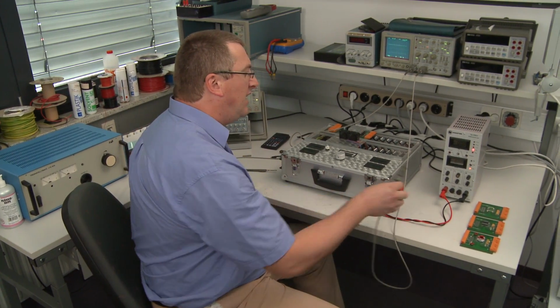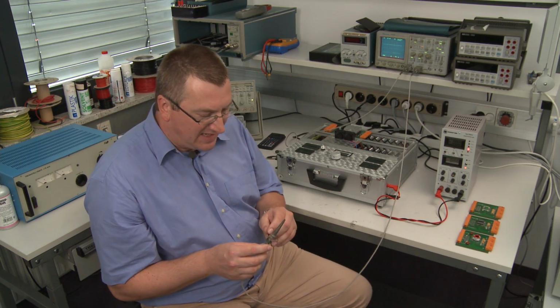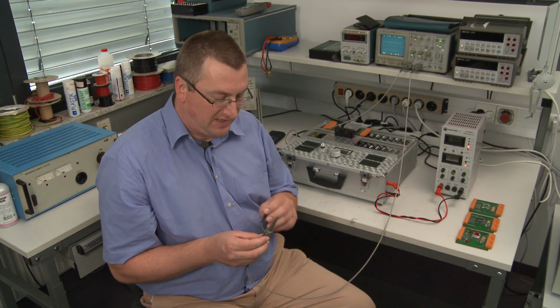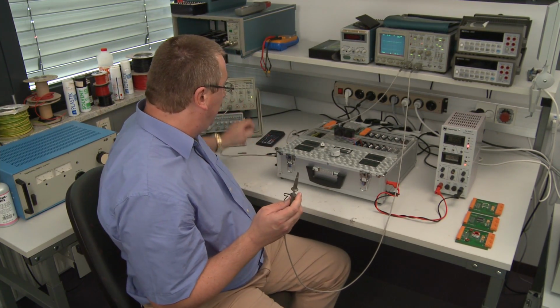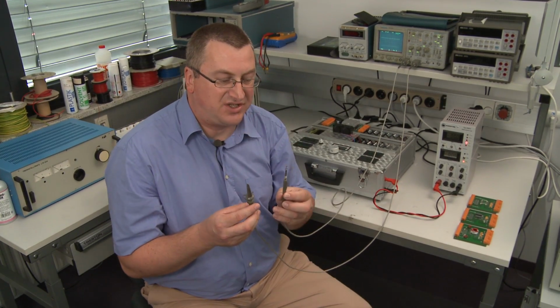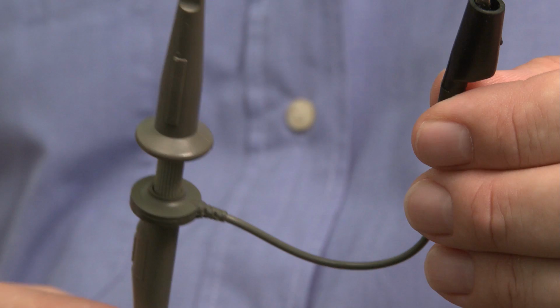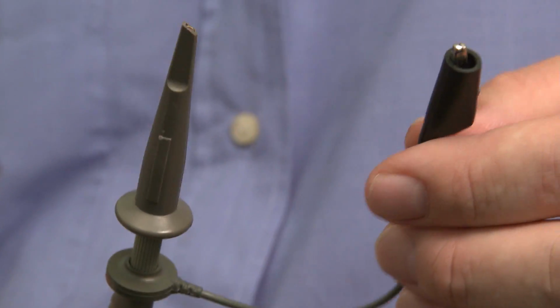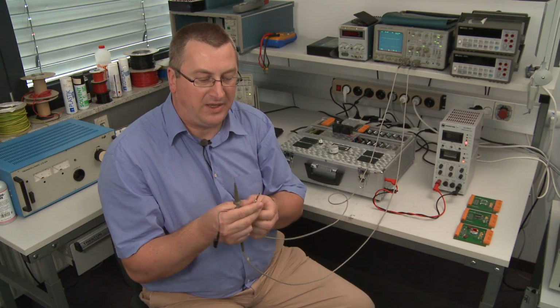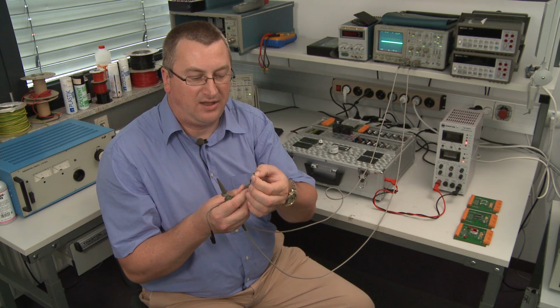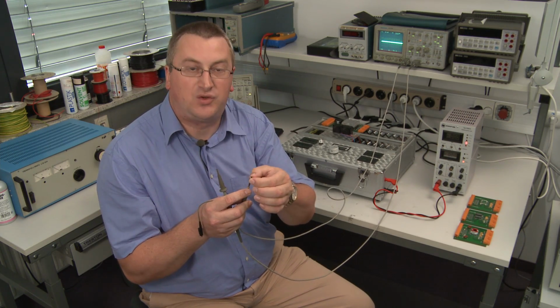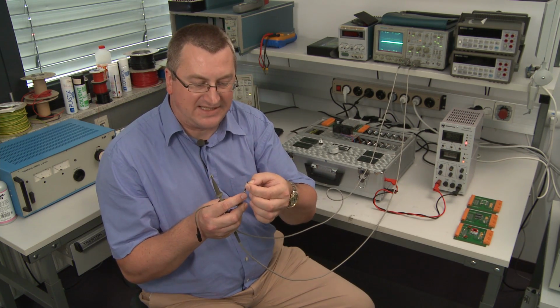First of all, I would like to give you some hints how to measure the ripple. For this measurement I made some changes in my voltage probe. I reduced the length of the ground clip by removing the ground clip and adding a special measurement tool that I made myself.